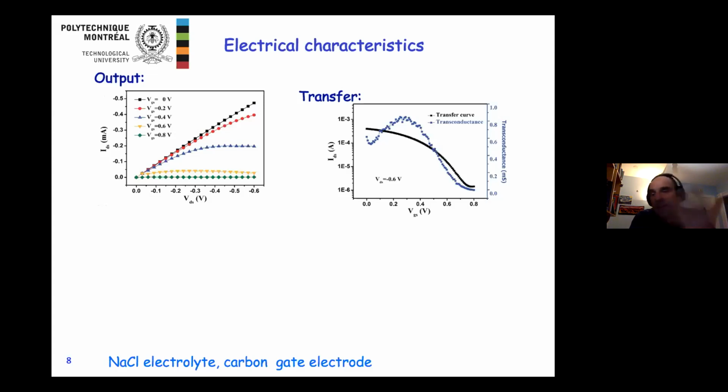So in this case, this is a little bit of a drawback, since most organic conducting polymers are conducting in a doped state. So you can only switch this transistor off. You can only operate it in depletion mode. Now there are some new polymers that can also give electrochemical transistors operating in accumulation mode, but with PEDOT we are limited to depletion mode.